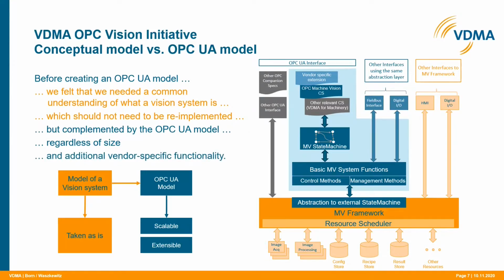And finally, the OPC UA server can of course incorporate additional interfaces, for example other companion specifications like the AIM, when the system is also to be addressed as an automated ID device, or vendor-specific interfaces. We expect that subtyping of the CS interfaces will be very common.